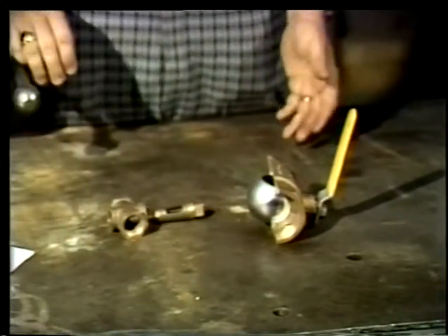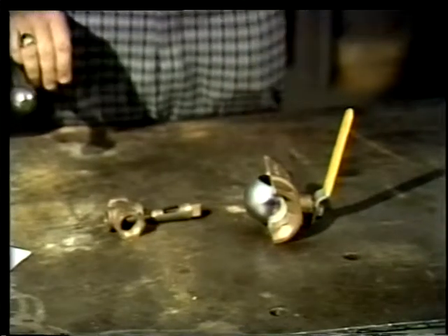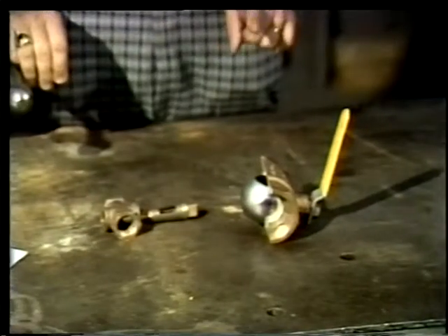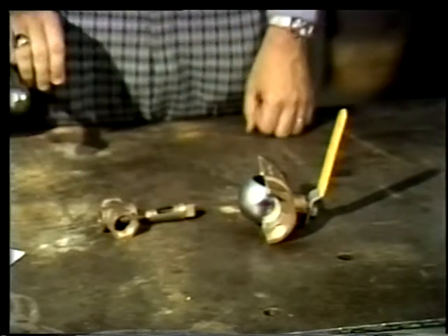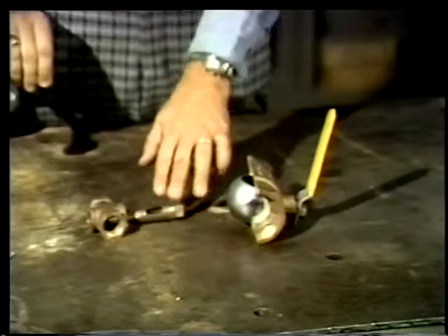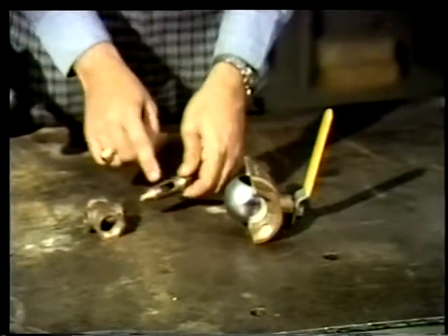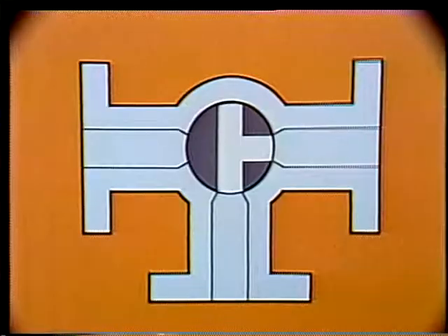Usually this design does not provide the same tight sealing quality of the globe valve, but these valves aren't generally used in systems requiring a tight shutoff. Often you'll see plug and ball valves on lubricating systems, such as on a duplex strainer. A plug or ball valve can be single port, or it can be a multi-port valve.